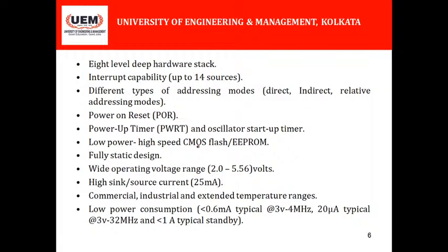Whenever we are retrieving an operand via a register, it is register indirect. Whenever we are retrieving an operand from a memory address via another memory address, it is memory indirect. Then relative addressing mode may be PC relative, base address relative, index register relative, etc.